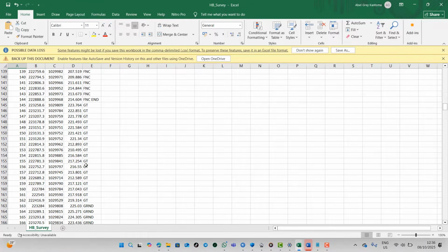You can see this is gate, GT gate. This gate is actually very, very important when you are doing your road design as well, because you already have some existing building structures. You don't want your road to be too far from the gate level in terms of height, whether it is too high or too low.